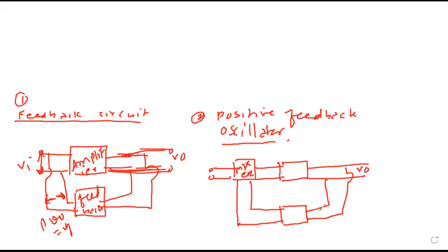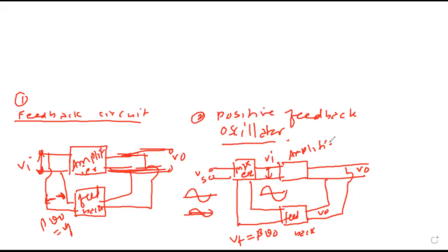So this is output which comes here from feedback circuit. Part of output is obtained, and this is signal here. This is input. So signal voltage and this feedback voltage, they are in phase with each other, and this way we get output which is applied across amplifier. So when input signal, feedback signal, they are in phase with each other, then this feedback is called positive feedback oscillator.